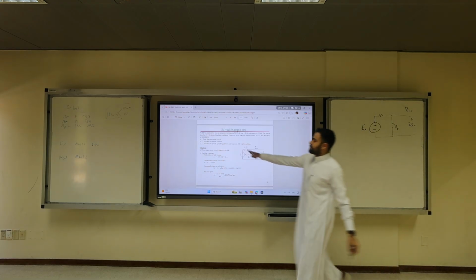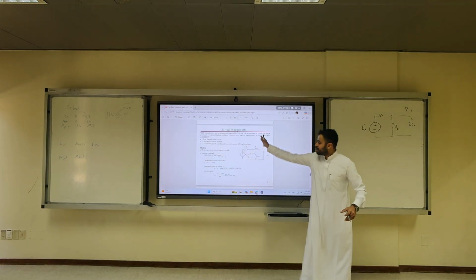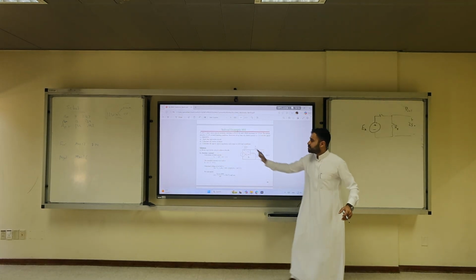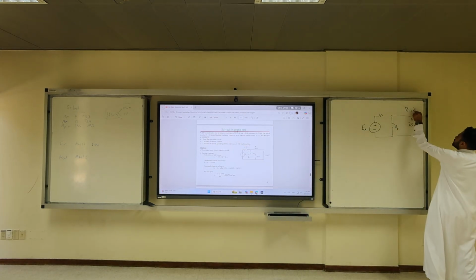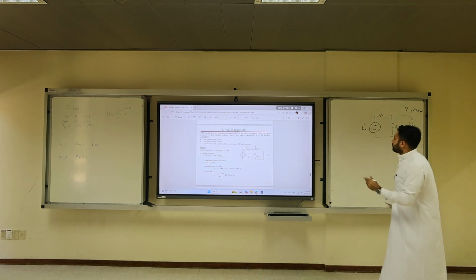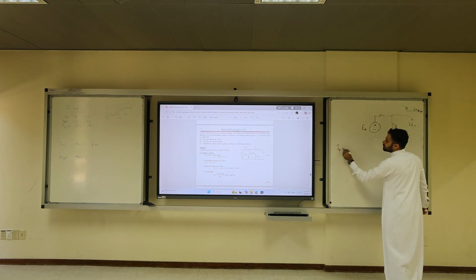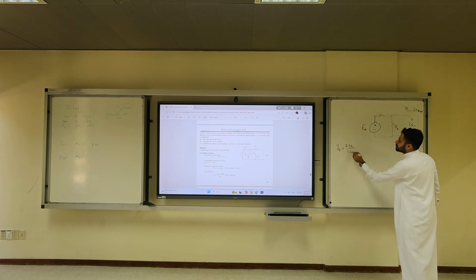What is your input power? This is not clearly specified, but it absorbs 25 kilowatt. This is the whole motor. The whole model absorbs 25 kilowatt. This means it's the input power. Okay? Now, we calculate IF. What is IF? 250 over RF. What is RF? 125. So it's usually a small current, 2 amps.